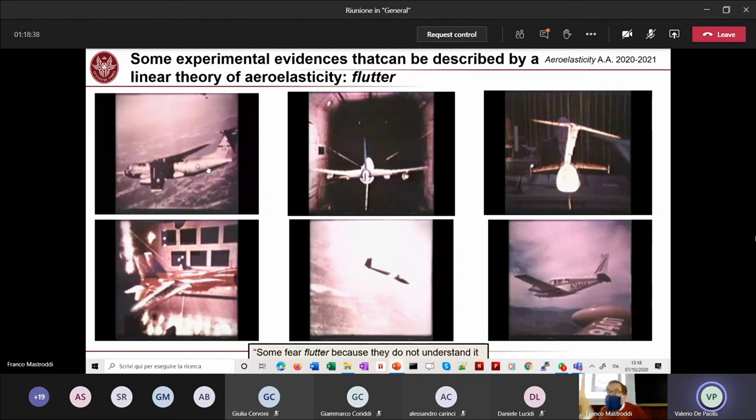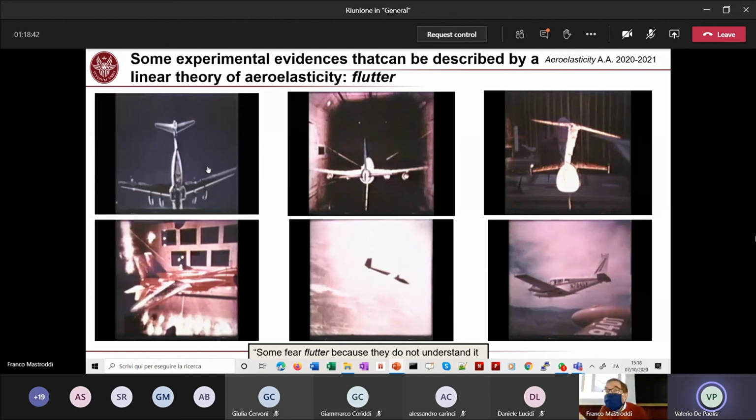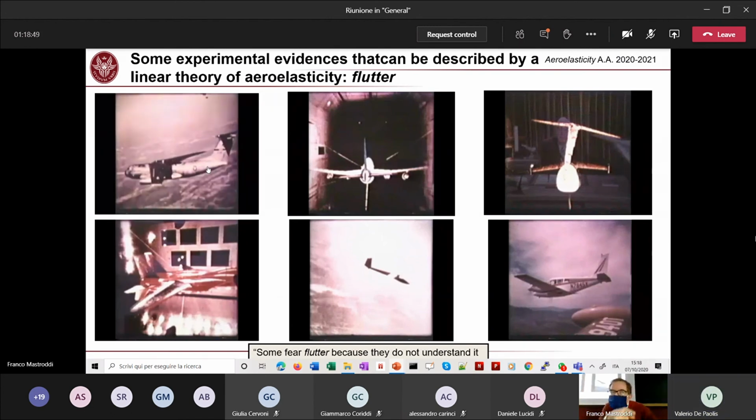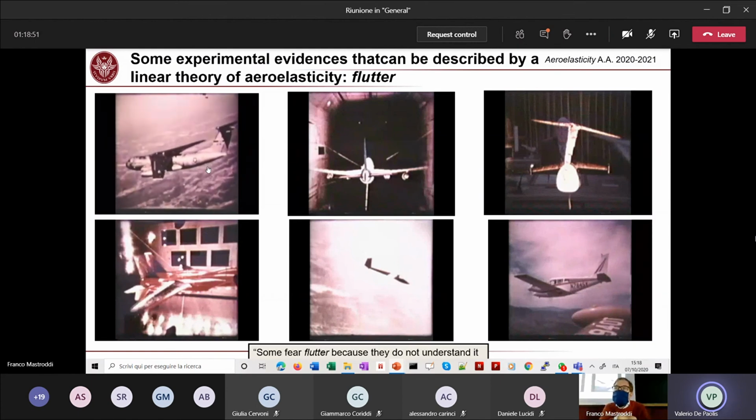Probably you are further, you are after this limit, and you are having a lucky day because the nonlinearities are able to limit this oscillation in a limit cycle. So what you see in reality is a limit cycle oscillation. The stabilizing effect, as you said in the first lesson. Right, because I can't believe that you are such a good experimentalist able to fix your parameter exactly at that frequency.